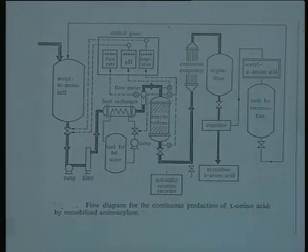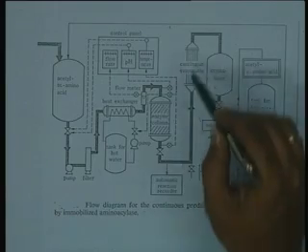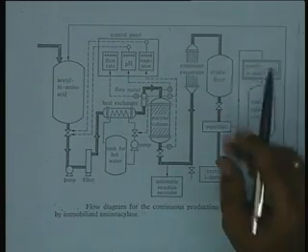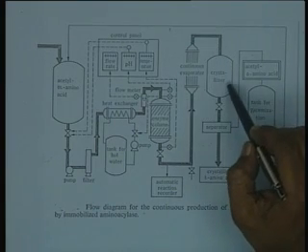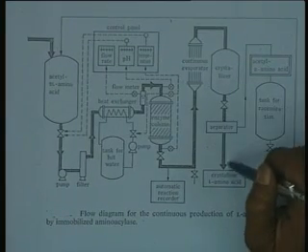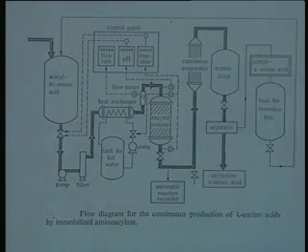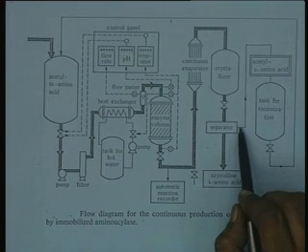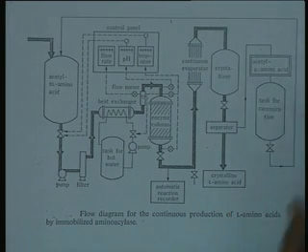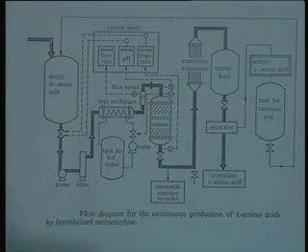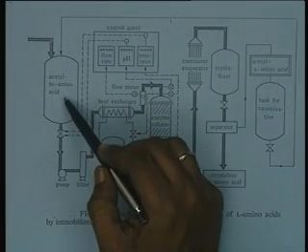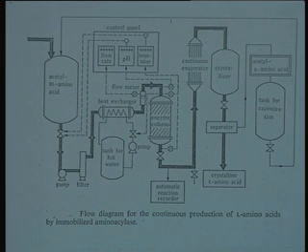Then the final product from the packed bed column goes to a concentrator, where it is concentrated just to take advantage of solubility and crystallization, and the L-amino acid gets crystallized and separated. Obviously, crystallization being used as a method is a very favorable method for purity of the product. And the D-acyl amino acid then is separated and taken to a separate tank for racemization, where pH is changed and racemization occurs, and this racemic mixture is again fed back to the tank, and again goes through. As a matter of fact, the whole process produces almost 100% conversion of DL to L-amino acid ultimately.